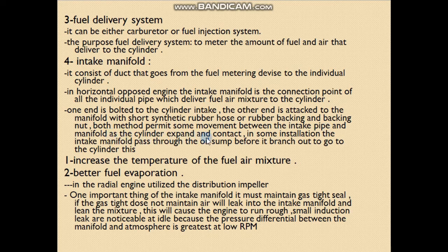This allows for the cylinder expanding and contracting. In some installations, the intake manifold passes through the oil sump before it branches out to go to the cylinders. The benefit of the intake manifold passing through the oil sump is, first, an increase in the temperature of the fuel-air mixture.